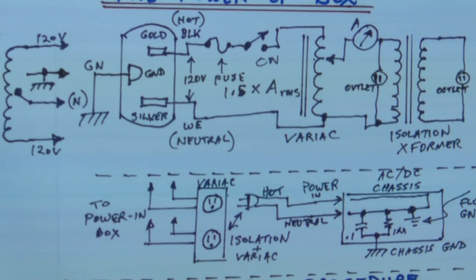First, this is my power add-on, or power-up box, and I'm showing you what I have. Then we go back to the plug, to the receptacle. Of course, we'd have a plug that fits into this. And you'll note that on every power outlet, there's a short rectangular connector and a longer one. And then you've got the rounded one. The rounded one is ground, and usually there's a green wire coming off of that. The gold-colored pin inside is the hot pin. There's a longer rectangular one that's the silver pin, and that connects to the neutral.